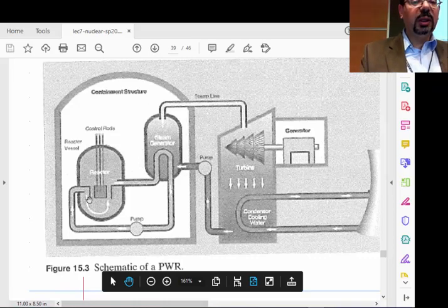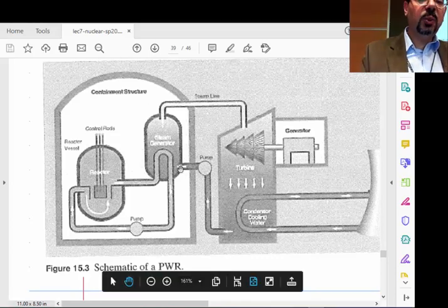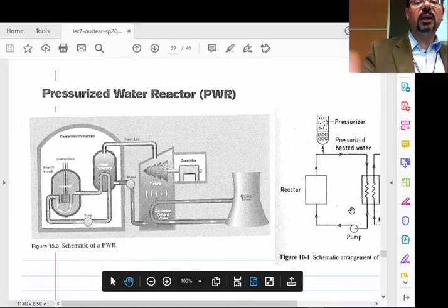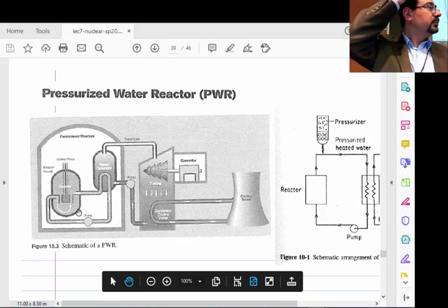So it goes between the nuclear reactor and the boiler, the actual boiler. And in the boiler, that hot water is liquid but very, very hot. That water heats the actual water that turns into steam, into the turbine, into the condenser, on and on. Okay? So we can tell it's a pressurized water reactor if we see the water going into the reactor never turns into steam, but instead goes into a circuit of its own. Right?